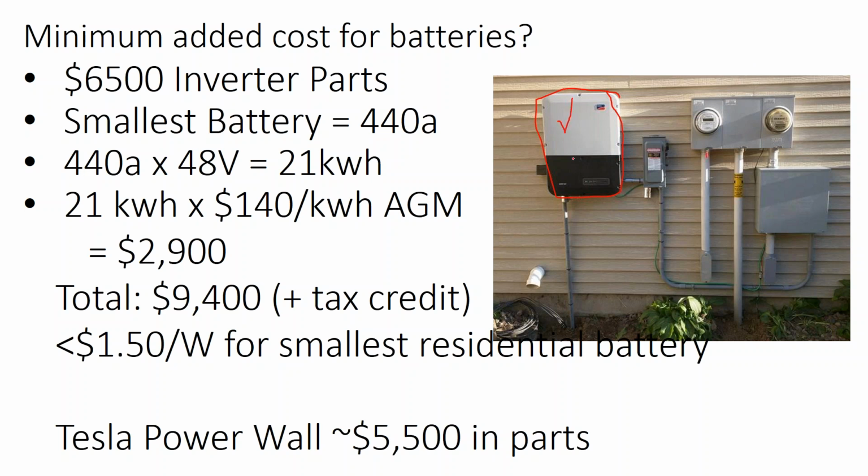But what SMA does get us is two things right off the bat. One, the SMA inverter is able to curtail the power output, so that when we do add a battery inverter down the road, we're going to be able to use more of the solar array and less of the battery bank, because we'll be able to take advantage of that feature.